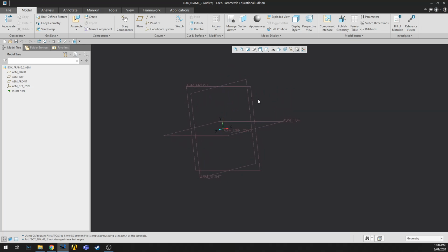And now we've got started. There are many ways to do different things. The way that I have learnt to do things, and I think it's a pretty neat and clean process when you're making framework parts, is first I would put in all my datum planes. So these here in front of us are datum planes. First I'll put in all the datum planes for the things that I want to make. Say it was the chassis, I'd have the datum plane for each place where I want to put the points. So the front bulkhead, the main roll hoop, the front roll hoop, and the back.